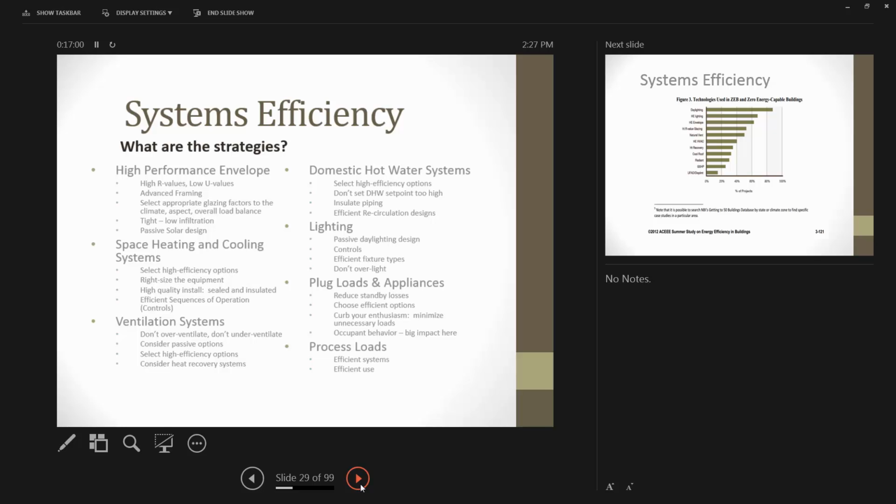understanding that if you're going to take a certain approach, whether your approach is going to be to add insulation into this wall system, understand that that's going to have a cause and effect on all the other systems in the house. So is it going to create a positive solution multiplier? Is it going to help reduce the heating load? Is it going to help the occupant comfort? Or could it be creating an unintended consequence? Try to keep that in the back of your mind when you're thinking about all these different systems.